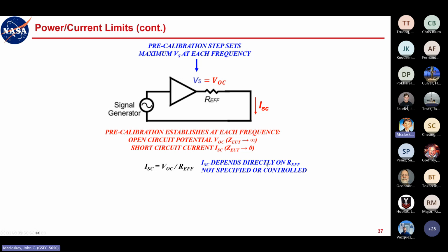The traditional amplifiers used for CS101 generally have a physical output impedance of 2 ohms, which maps to half an ohm at the transformer secondary to match the half ohm calibration load. But that's not specified in the MIL standard, and I'll talk about a couple of cases where that can get you in trouble.